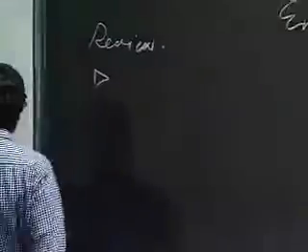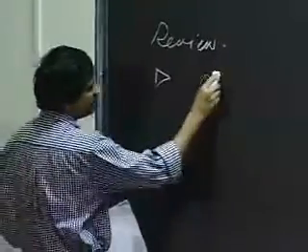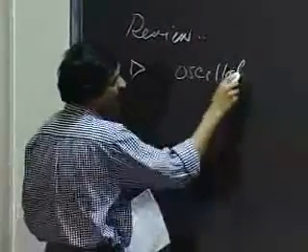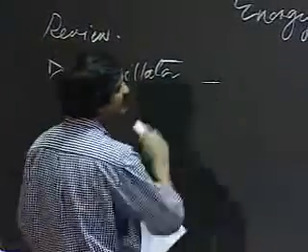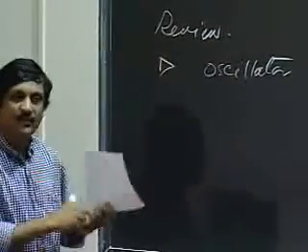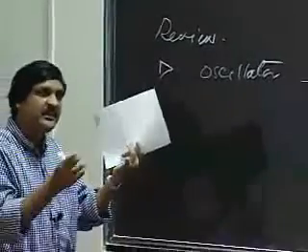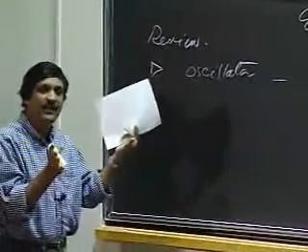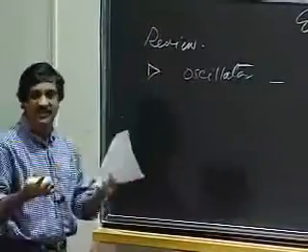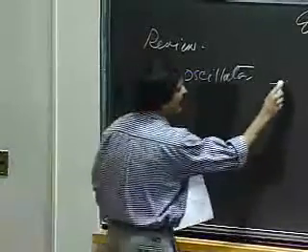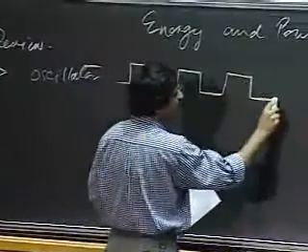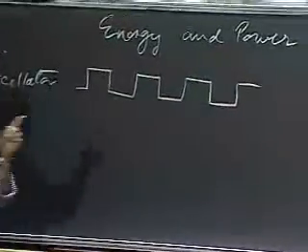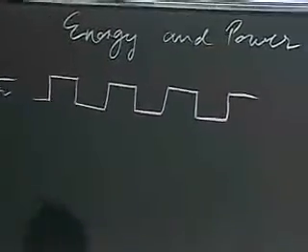In particular, we built an oscillator that allowed us to charge a capacitor, and when the voltage across the capacitor equaled that at the minus terminal, it would flip and keep doing so. At the output, you would get a square wave output.